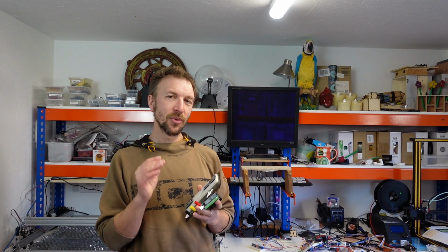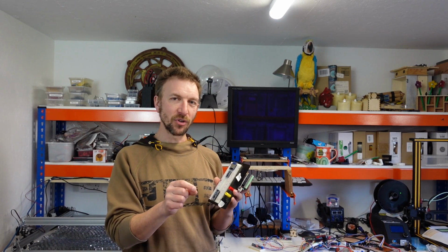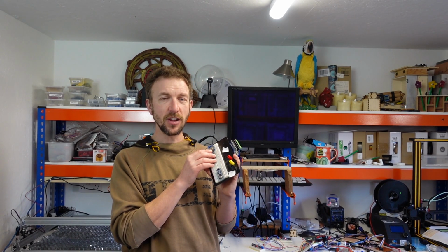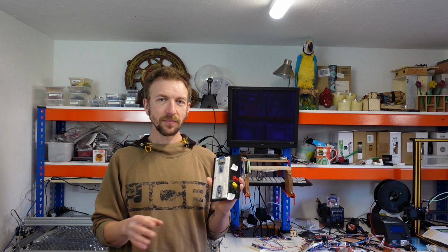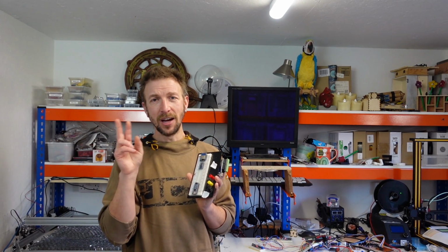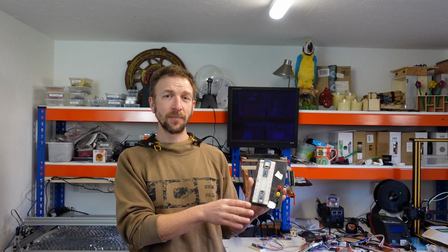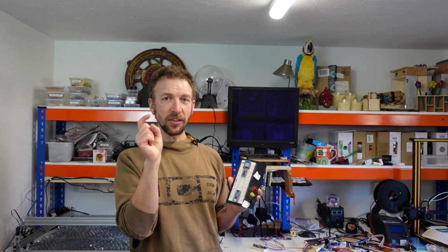And instead, what I'm going to do is add a serial connection between an Arduino and an ESP32 on the master controller. So the master controller is going to have 2 processors on it. It's going to have the ESP, which is going to do all the game functionality. It's going to do the display and the timer and all those things which I've already coded on it. And then I'm going to have the Arduino, which is going to do all the sending and receiving commands over the network to the devices, which is the thing which is already running on it. And then I'm just going to pass messages between the 2 using a serial connection.